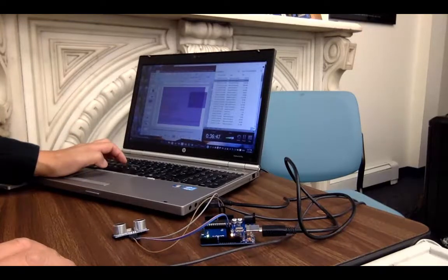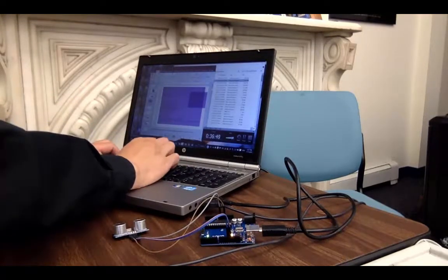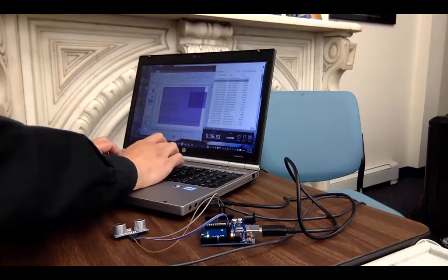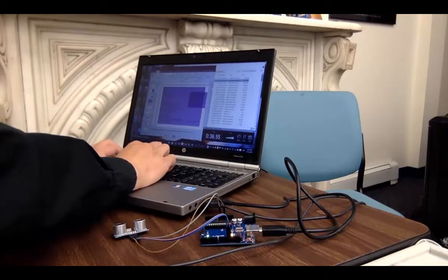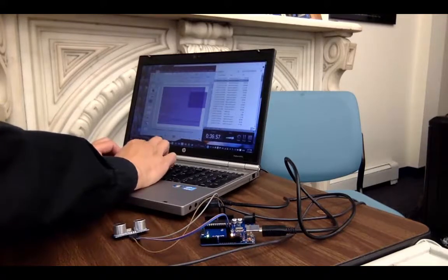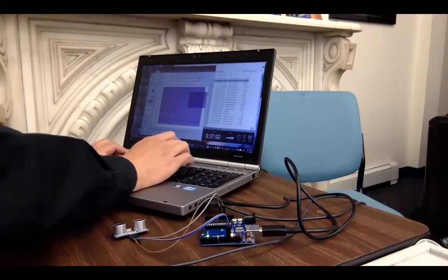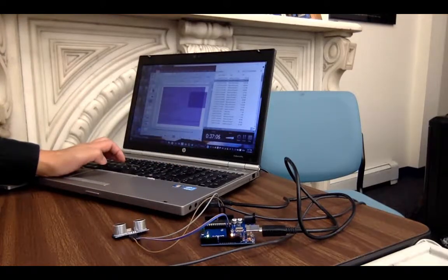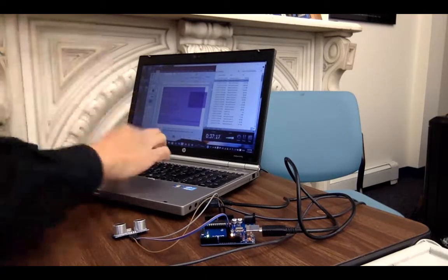And in this setup, you have to say pin mode, and then this trigger pin is output, which means the signal needs to be sent out from your trigger pin, like a chop. Your sensor needs to chop and then receive the echo.